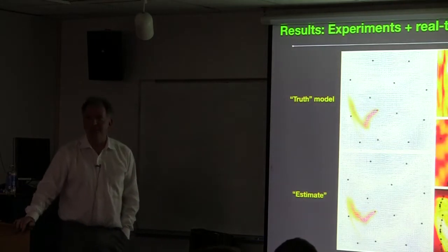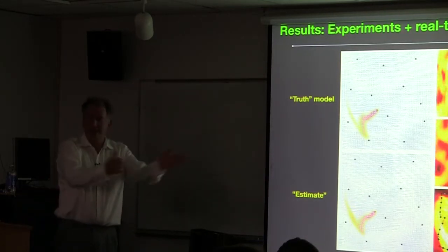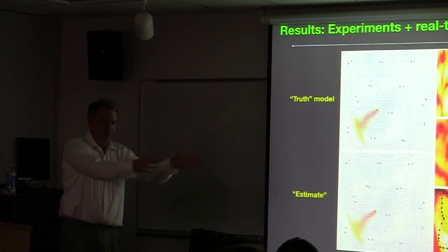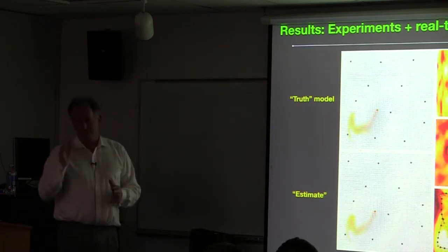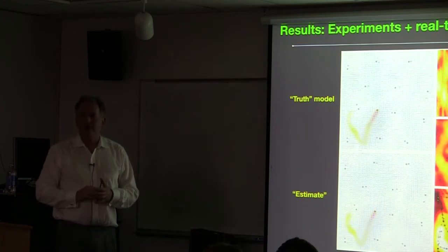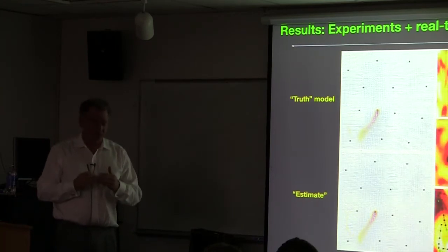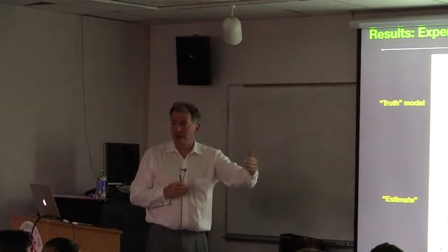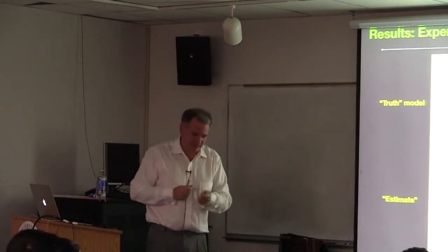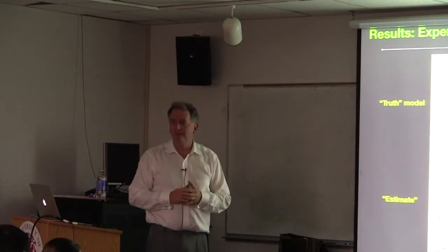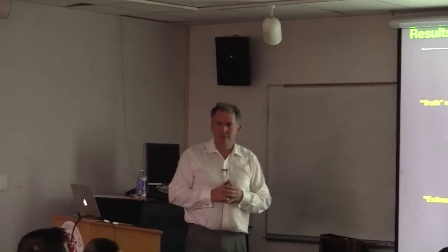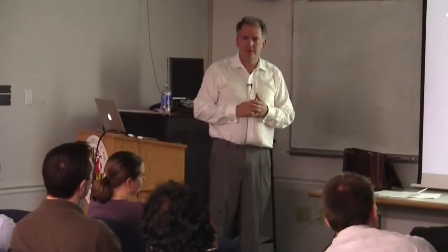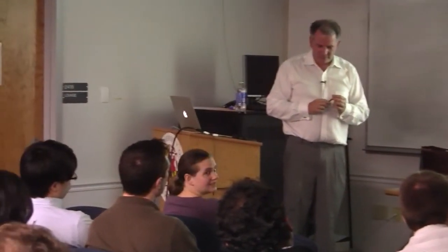Y depends upon C, but I can optimize the location of the sensors to optimize what the C matrix is in a linearized description of this problem, which is an important caveat, without knowing exactly what measurements I'm going to take between now and the forecast time, to show how I'm deviating from the central trajectory that I think it's going to go on. So at what point do the measurements affect it? Because otherwise, if the measurements never affected that covariance estimate, then the path would just be pre-planned completely offline, right?